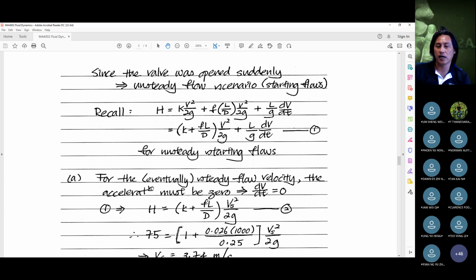But what I'm going to advise is always start out with the full Bernoulli's equation, because that will let you account for all the various types of pipeline that you're going to encounter out there, not just this higher reservoir, lower reservoir connected by a pipe. Over here, I did not use the full Bernoulli's equation, but you should start out with the full Bernoulli's energy balance equation as a first instance, and simplify the terms before you get this, just to make sure you are able to account for different types of scenarios.